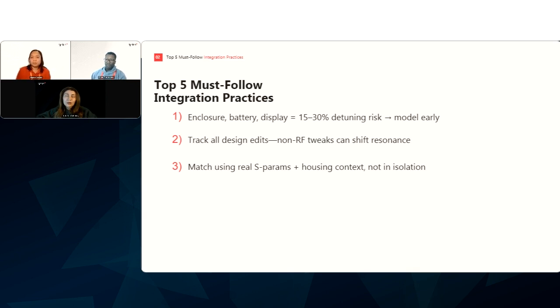I think that's well, at least in antenna, if we talk about antenna engineers, everybody in this field knows that matching is really fine tuning, really important, and that is actually what brings your antenna from simulation to the real world, right? So you tune your antenna to work in the real world with the real environment. For example, if you design an antenna for a wearable that's supposed to work on the body, you need to tune it on the body as well.